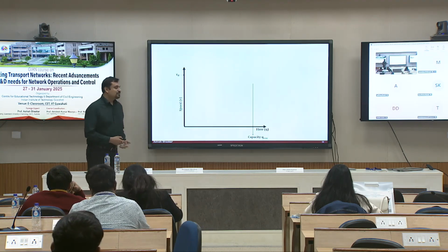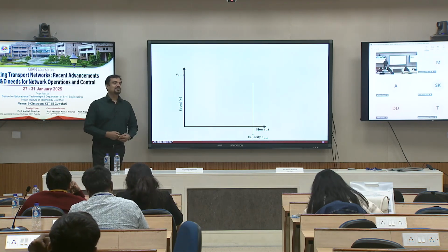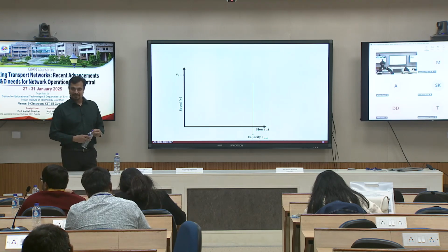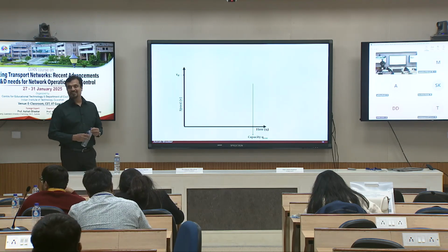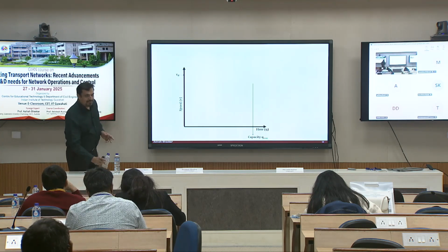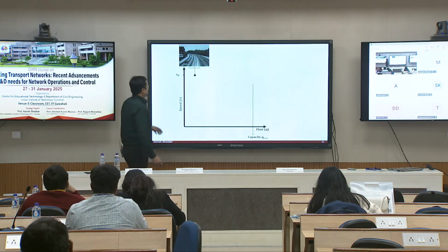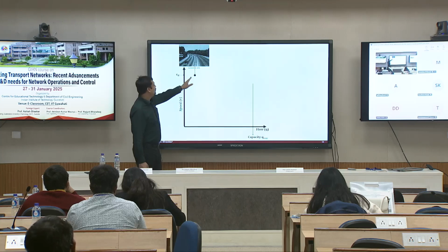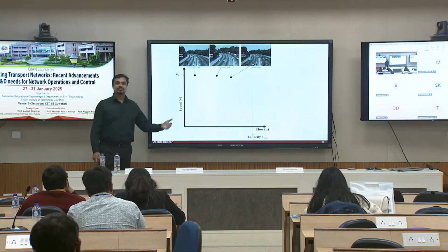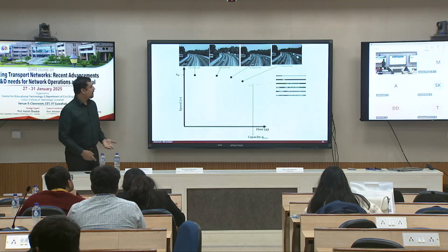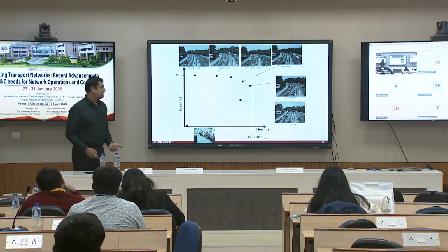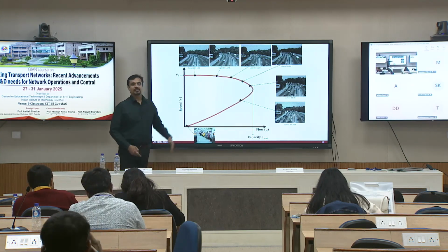Then draw the diagram between speed and the flow now. Speed flow relationship. Yeah. Speed and the flow, how does it look? Yeah, okay, good. Same thing, the boundary conditions. Hardly any traffic on the road, flow is quite low, speed is free flow. You have a free flow speed for a while, then the speed starts decreasing as the flow starts increasing. You reach the capacity. After this, things move in the congested region, and you get a curve like this.